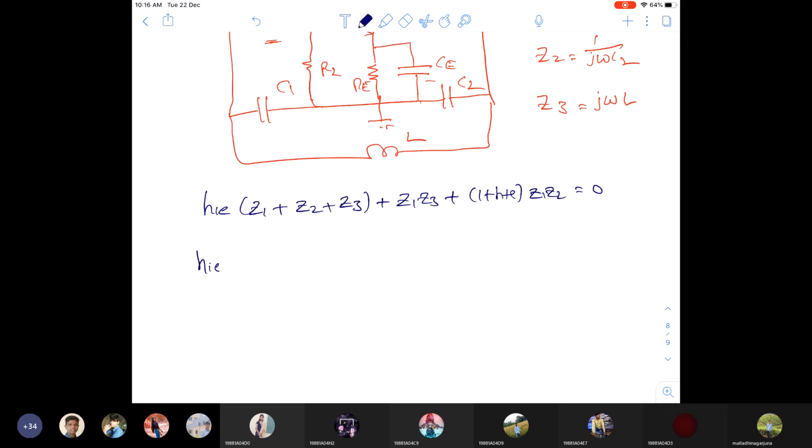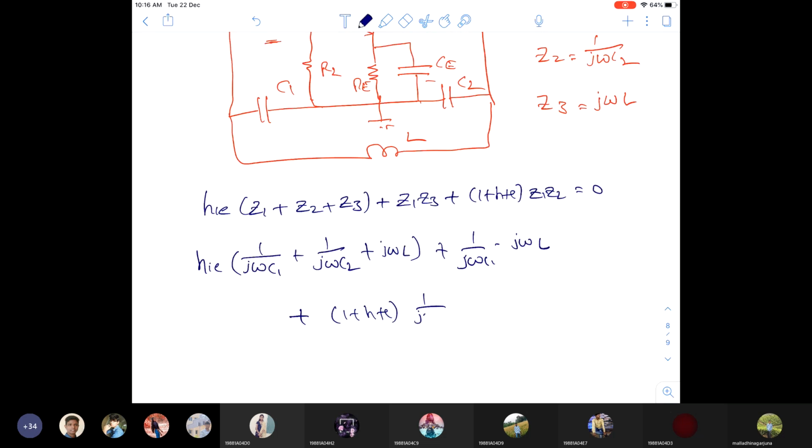So substitute: hie into (1 by j omega C1 plus 1 by j omega C2 plus j omega L) plus (1 by j omega C1) into (j omega L) plus 1 plus HFE into (1 by j omega C1) into (1 by j omega C2) equal to 0. Okay.